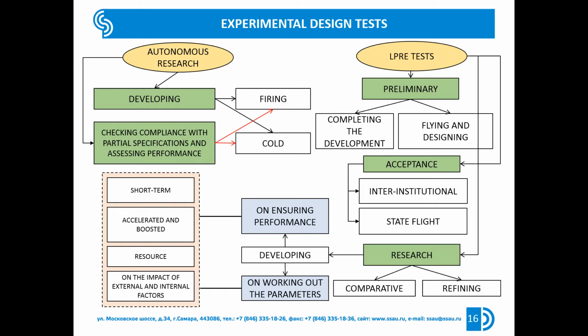The entire scope of testing during development work is carried out in accordance with a comprehensive program of experimental testing of a liquid propellant rocket engine, which is designed so that the required technical parameters and reliability of the new liquid propellant rocket engine are achieved in the minimum time and with minimum cost. Unlike research, development tests are carried out only on actual constructions of a unit under development or a liquid propellant rocket engine as a whole.